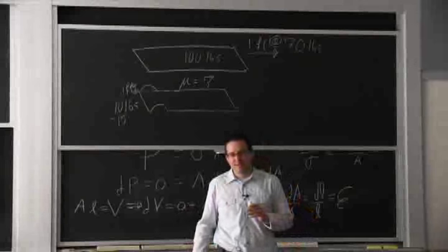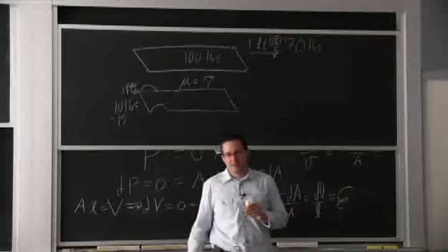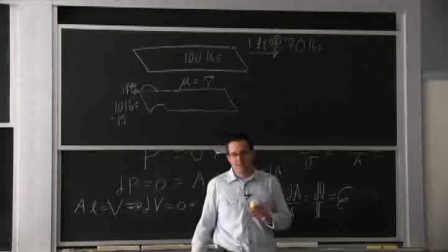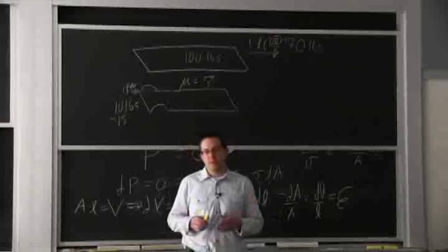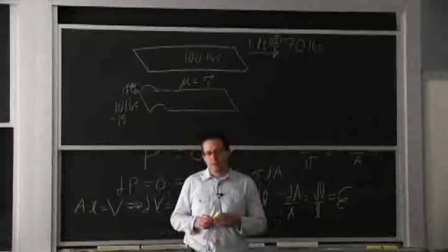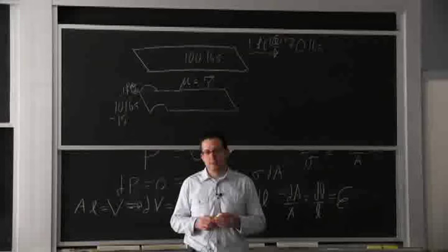Yes? So if you do tension on all sides, volumetric expansion, it doesn't yield ever. You were saying you need to have a difference in stresses on all three sides. Yeah, if it's just a pressure, then you're just changing the distance between the bonds. So if you have a compression, it crushes eventually. Well, what happens when you have tension all the time? It will never yield.